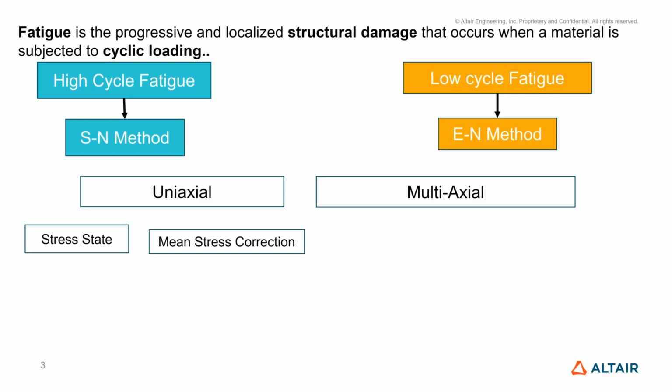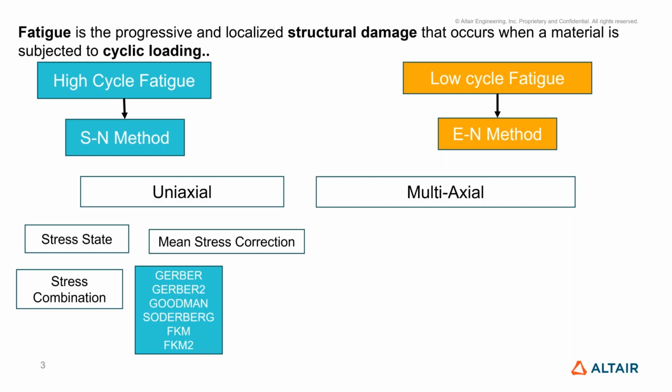In the uniaxial approach for solving fatigue evaluations, the models with uniaxial loadings consist of loading in one direction, resulting in one principal stress. So SimSolid converts the stress tensor to a scalar value using a user-defined combined stress method. Gerber, Goodman, Soderberg, and so on are the methods used with the stress life method. With the strain life, SWT and Morrow methods are used under the uniaxial approach.